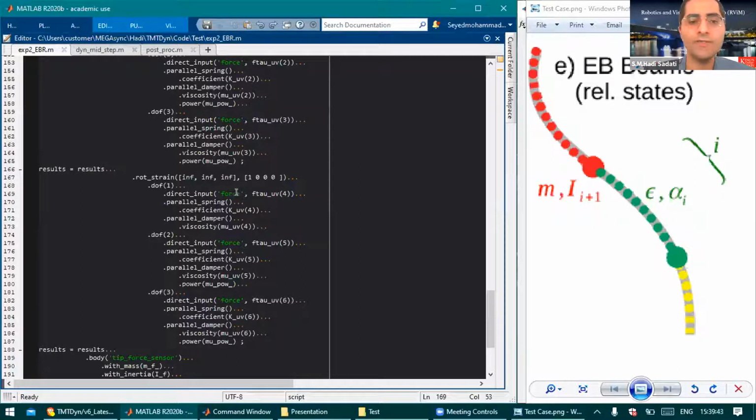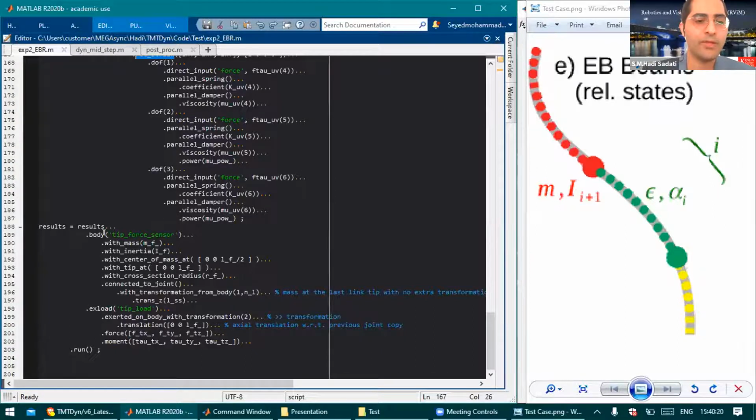Okay, you can set the direct input as position. When you have a force, it's like a direct force, but when you set it as position, it's like defining a geometrical constraint for that joint to move exactly like that. You see that I can define any rigid robot with this formulation as well. It's basically a way of formulating a robot, a continuum robot. But for a rigid robot, definitely you don't use strain, you just use rotation, and that gives you Euler angular representation. Okay, done.